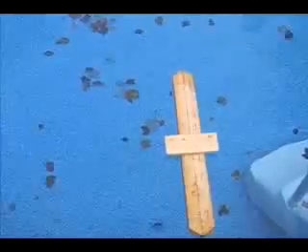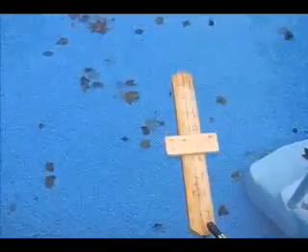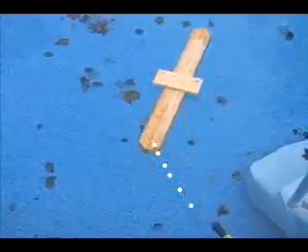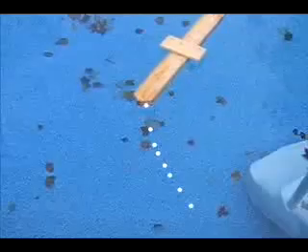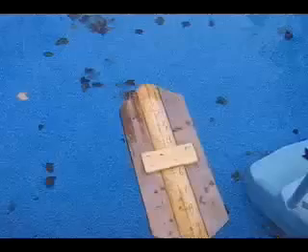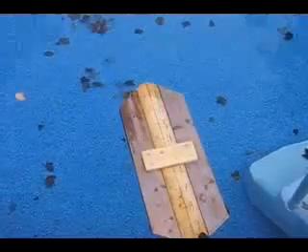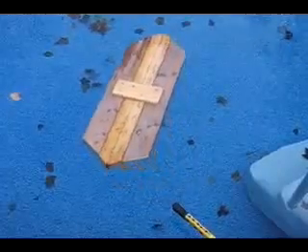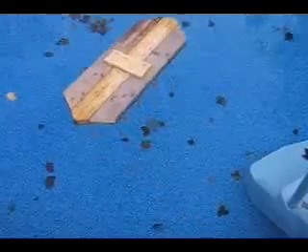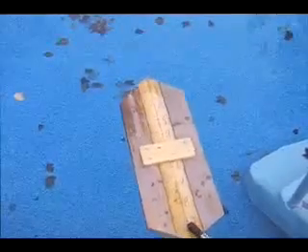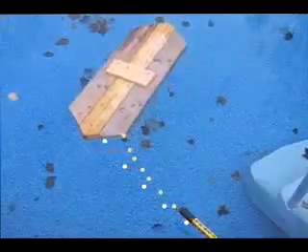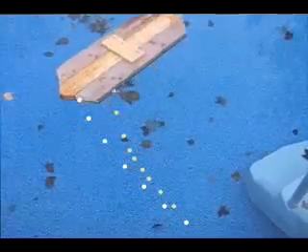Let's compare two ships with the same length, same draft, the first having only the third of the beam of the second one. After the ships have developed sideways motion, it is harder to stop the drift of the wider ship, 3 times heavier for approximately the same lateral resisting force. That resisting force being here the surface area of the wall of water, which is represented by the ship's length times the draft.